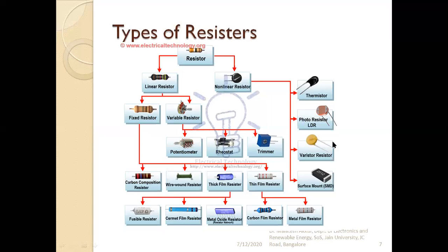We cannot connect the fans or ACs directly to the processor, because the processors work with just 5 volts DC. But the fans and so on require AC of 230 volts, which is very high voltage and produces high current.